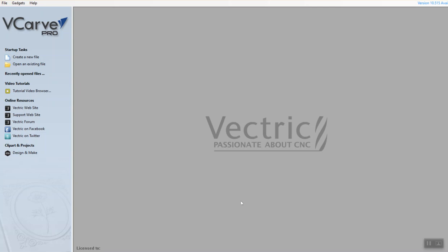But the difference is, after you create the 3D solid model inside the Vcarvepro, you're going to convert that into a toolpath. Toolpath is what is absolutely necessary for the Axiom CNC machine to accept. And so this is a two-step process, okay? And automatically it generates the 3D solid model into the toolpath, and you can just take a copy of the toolpath, take it to the CNC machine, and have the wood carved.